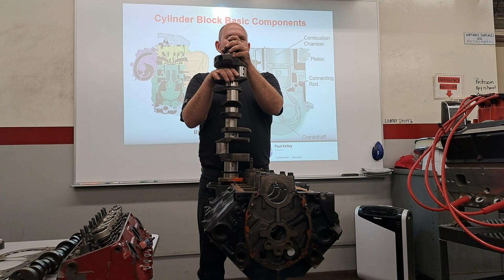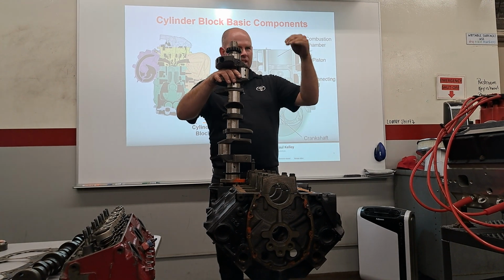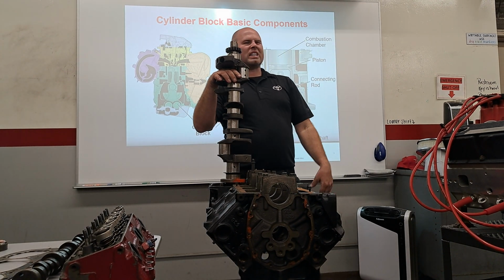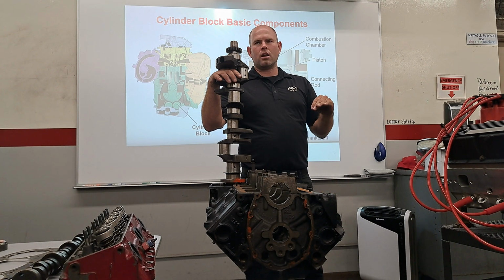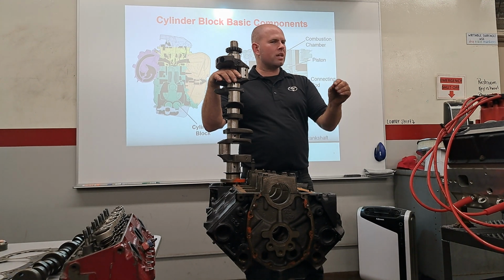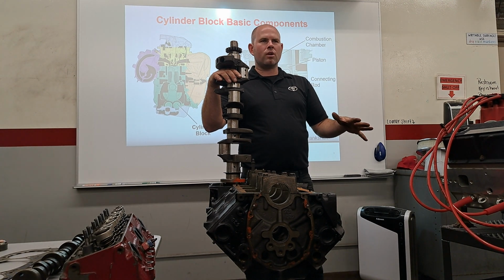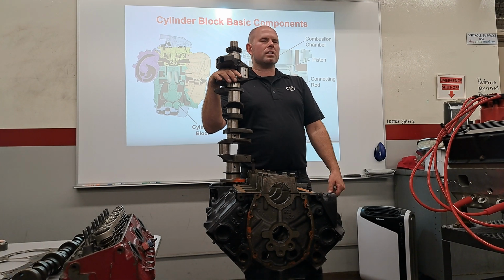What we did, we disconnected cylinder by cylinder. Cylinder 1, grrr. Cylinder 2, grrr. Cylinder 3, silent. Cylinder 4, grrr. It came back, right? So in cylinder 3, we disconnected it, the noise really went away. So we went back to him saying, we performed diagnosis, checked this and this, and found you have a bad number 3 rod bearing. Most likely other rod bearings will be damaged as well. You really need an engine.